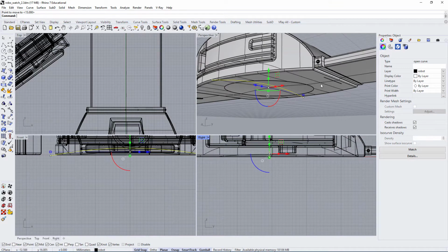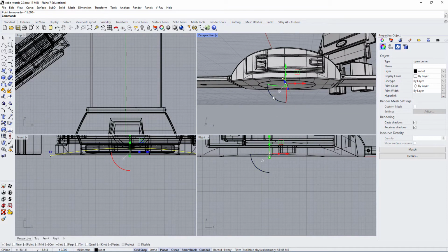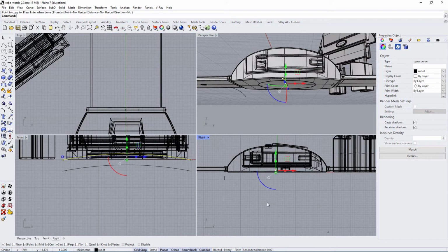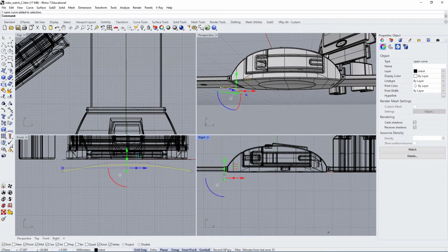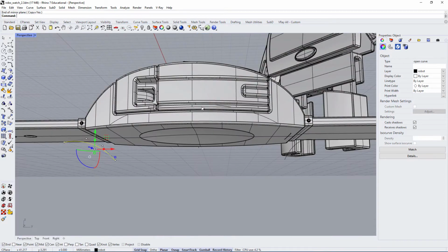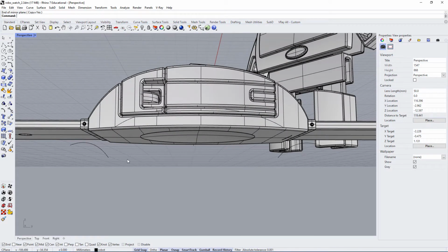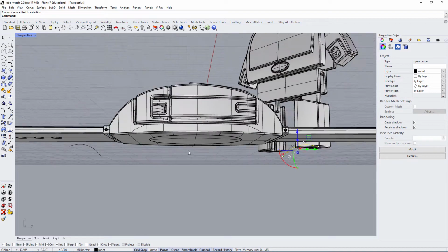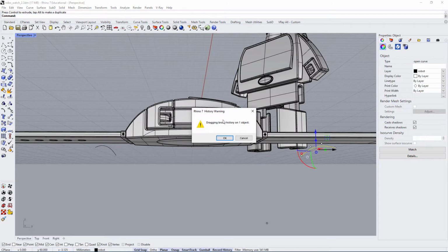And let's just make a simple surface. Now you could revolve it, or you could copy it. Let's copy it here, and let's use the record history. I will use the always record, and I will use the mirror command, mirror one curve to the other side. So now if I make any kind of edits, you can see the right side is moved with the left side. And if I do the opposite, if I move the mirrored curve, it breaks the history.